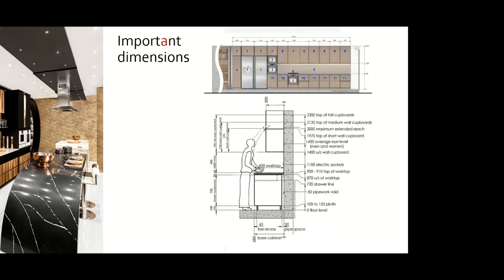These are basically standard, you might say, industry sizes when it comes to plinth height and base unit and also your wall unit heights. And again, these are not cast in stone. It depends on various factors determining what you're going to use in the height placement for cupboards.